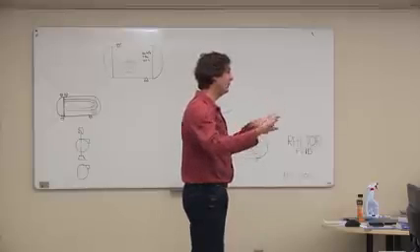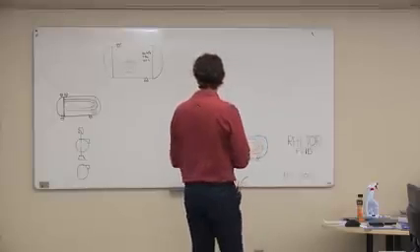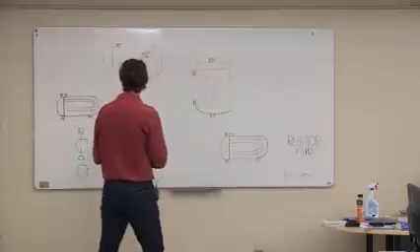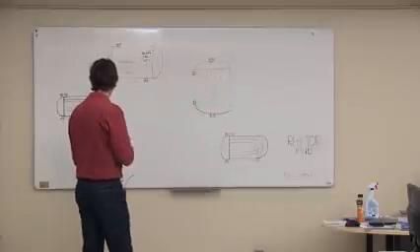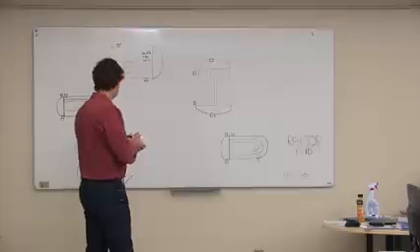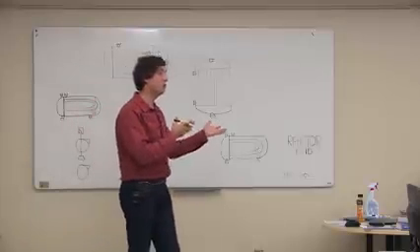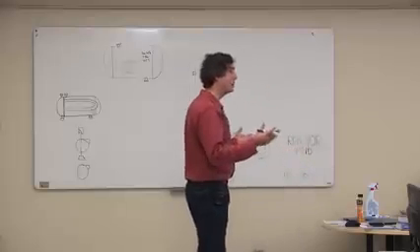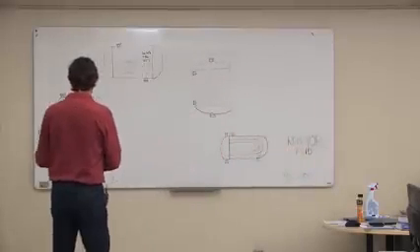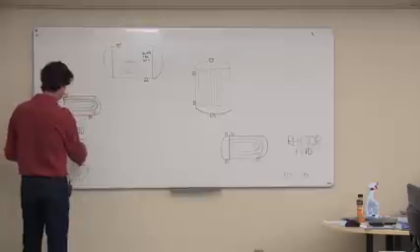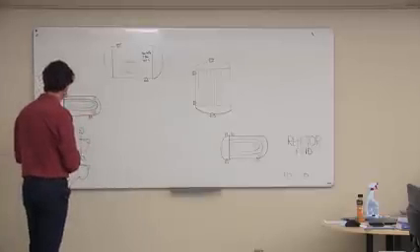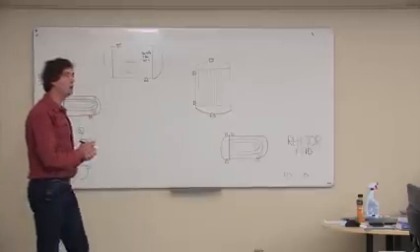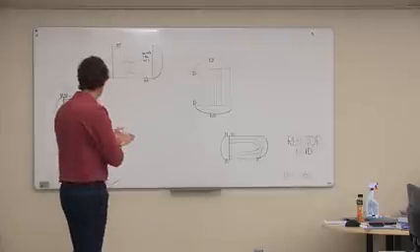In either way, we could run one or two of the pumps with a backup system. So the other thing you also want to do is have two pumps, because it could be a power failure, but it could be just a failure in the pump as well. So we would definitely want to have redundant pumps here. Can you follow that sort of line of thinking? Does that make sense to you guys?